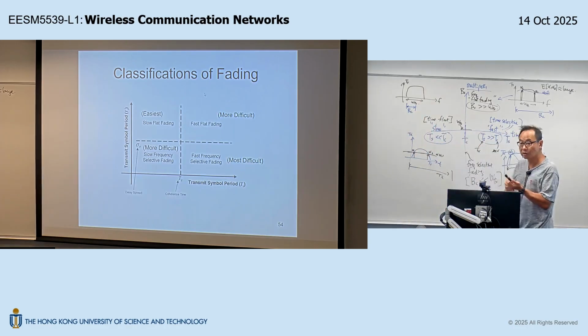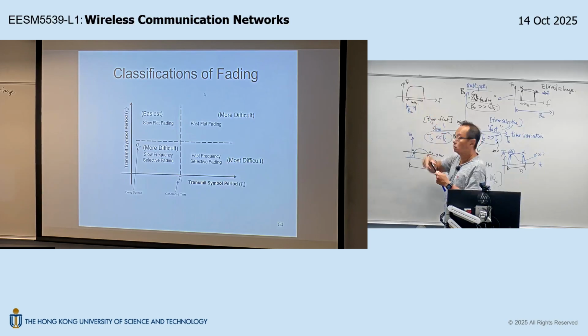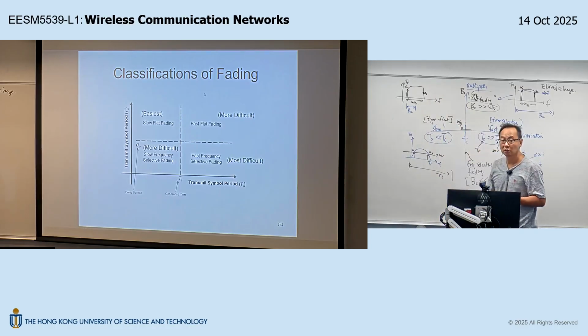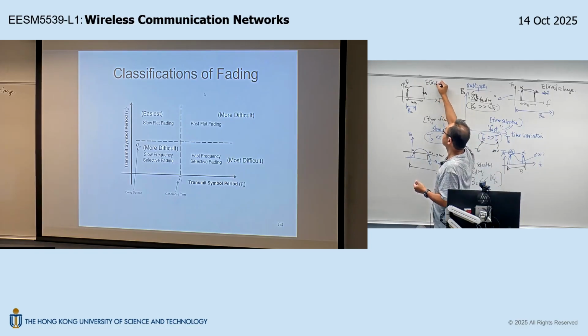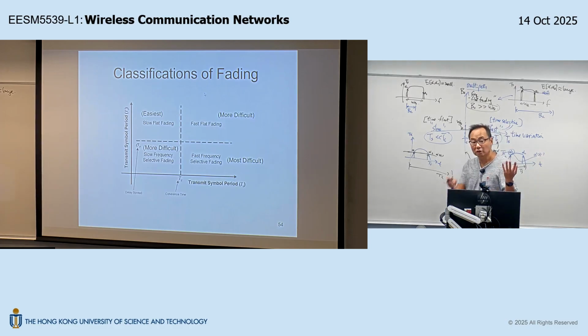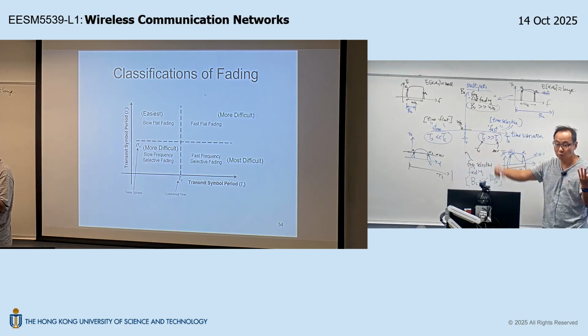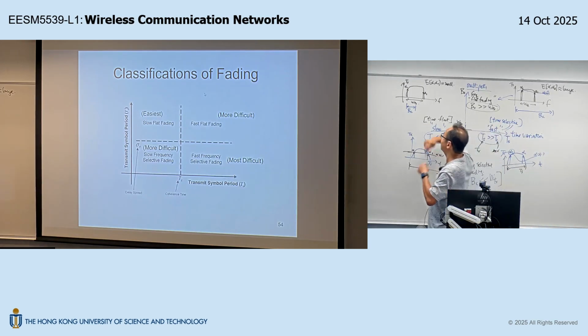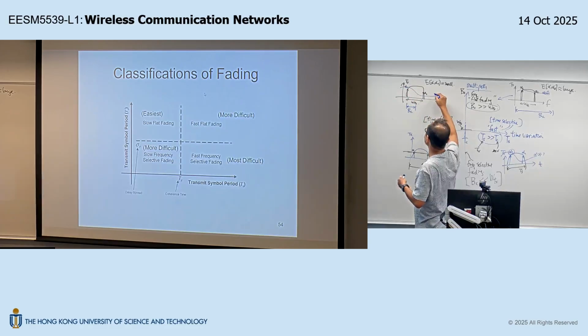Then what happens is, the first frequency components that you transmit may experience a certain alpha 1. At the end of your transmitted spectrum, you may experience another fading coefficient. Now in this case, the fading coefficients are uncorrelated. What does uncorrelated mean? That means if you look at alpha 1's realization, let's say alpha 1 is large, it doesn't affect the chance for you to see alpha 2 being large or small. Alpha 2 can be small in general, with high chance. So if you try to plot, the response will look like this.